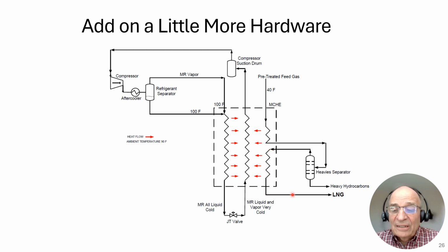So you have now LNG being produced using an MR compressor. Something very wrong here. You're going to go from 100 psi to 750 or so psi in one stage? Not really. So let's put in multiple stages of compression and do some other finessing.